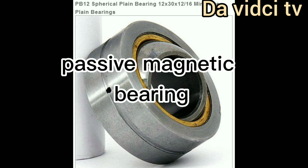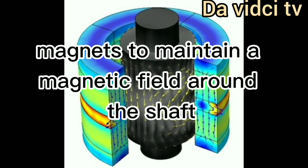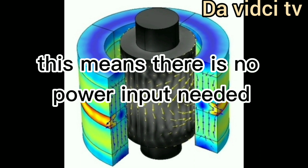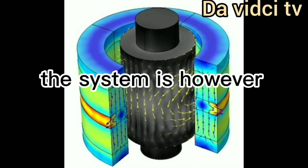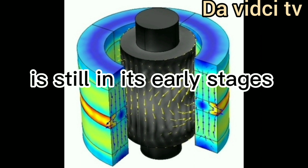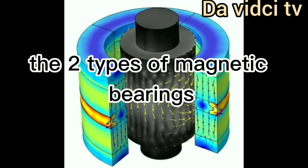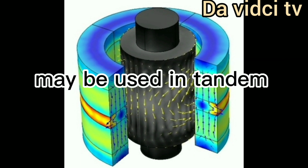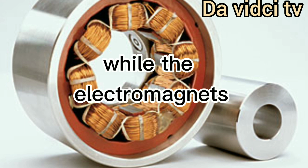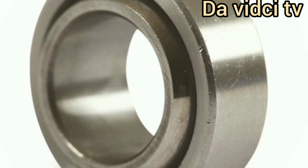Passive magnetic bearing. Passive magnetic bearings use permanent magnets to maintain a magnetic field around the shaft. This means there is no power input needed. The system is, however, difficult to design due to limitations, as this technology is still in its early stages. In many cases, the 2 types of magnetic bearings may be used in tandem, where the permanent magnets handle the static loading while the electromagnets are used to maintain the position to a high degree of accuracy.